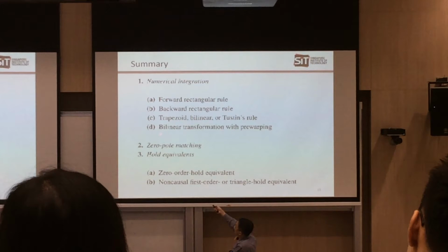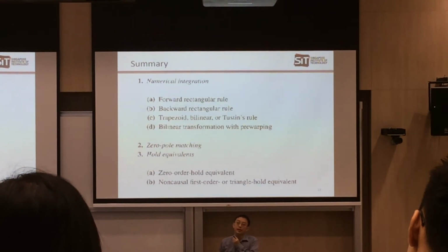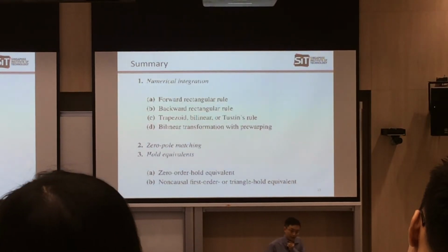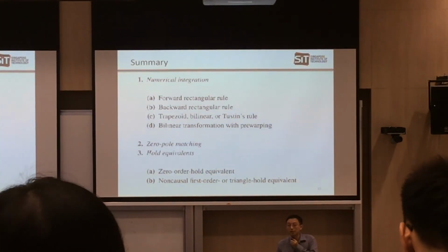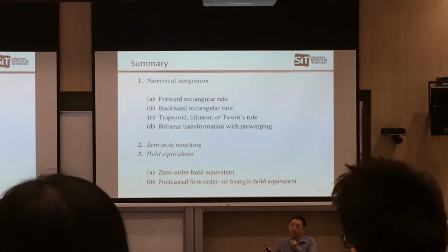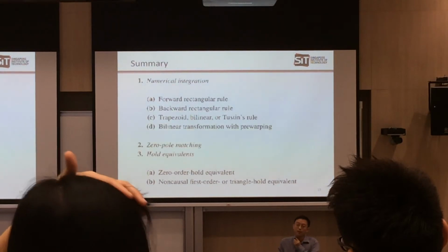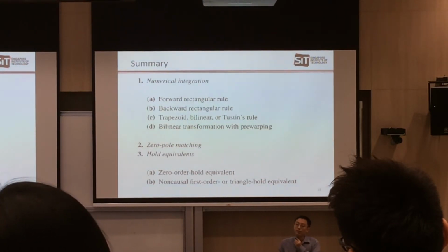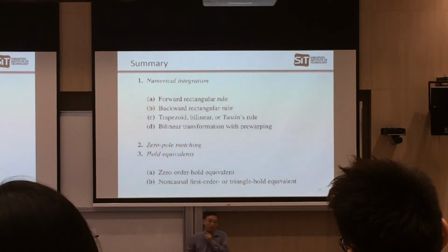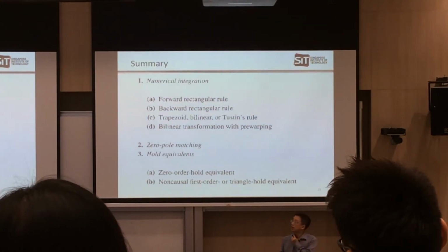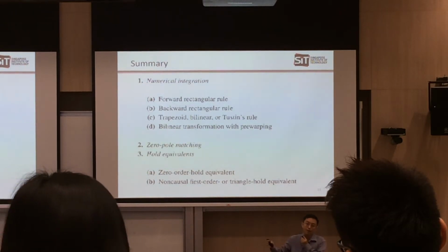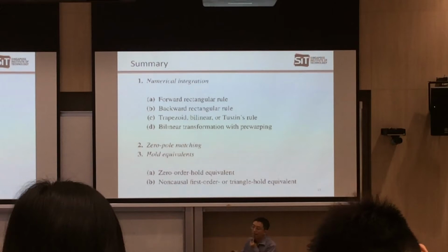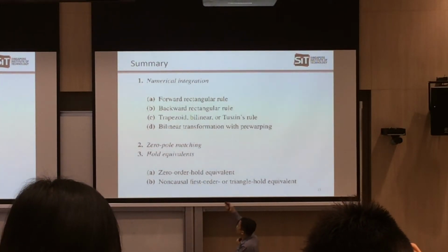Now we will do one exercise to show exactly how to do it. And today we are going to use the zero and pole matching. So basically, you find what are the zeros, what are the poles in your H(s) function. Then you just replace with e to the power sT. So you get your digital poles, you get your digital zeros. If you get any zero at infinity in your s domain, you map it to minus 1 in your z domain. So this is zero and pole matching. And lastly, we talk about the step invariant method. If you are taking the zero order hold, then we use your H(s) divided by s. Then look at the table, find out the z function. Then multiply with 1 minus z to the power of minus 1. Okay? So these are the three methods.